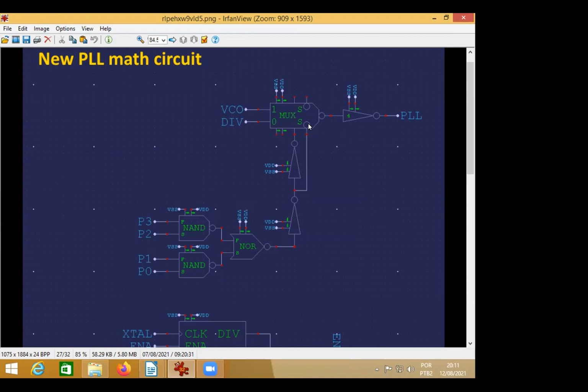That glitch blocks us from doing the on-the-fly change between those two. We cannot do that. But if you have a chain of ORs, receiving the VCO signal in one part of the ORs, they can be 3-input ORs, not 2-input ORs.